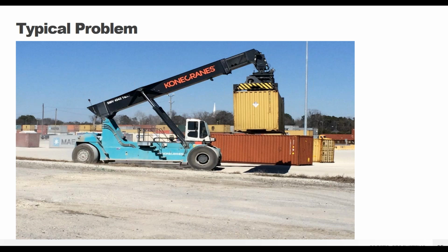This project consisted of a 100-ton reach stacker and it had a really soft subgrade. It has a CBR of 2%, which is really, really soft. So the reach stacker could only make a few passes before it would start causing ruts and get bogged down, and they would need to come in and try to repair the yard. And obviously that's just not practical.